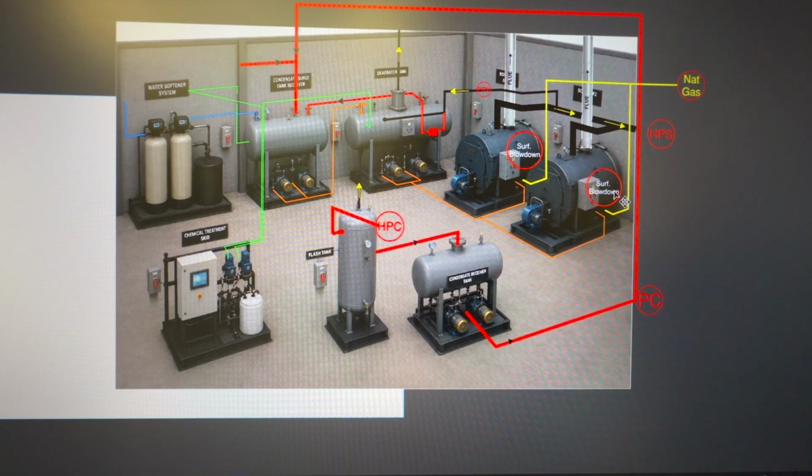The purpose of it is to maintain proper conductivity, remove dissolved solids, improve steam quality, prevent scale formation, and protect boiler efficiency.